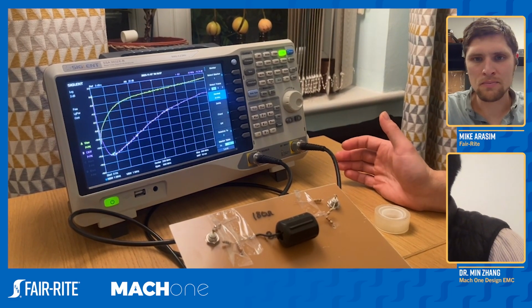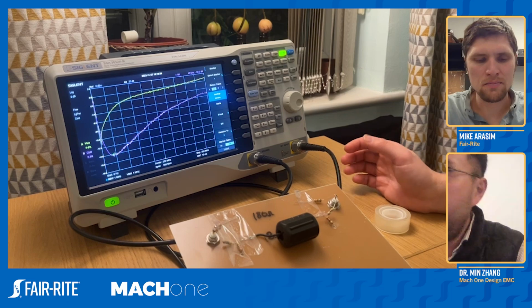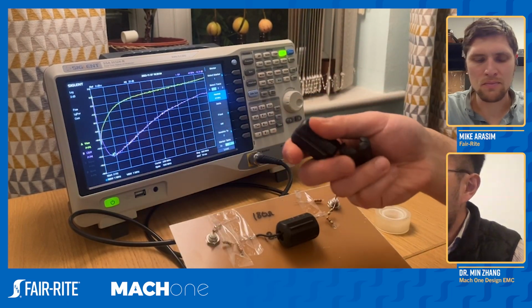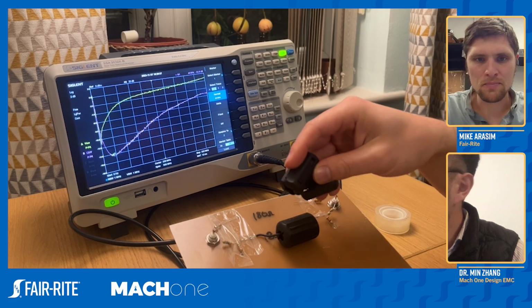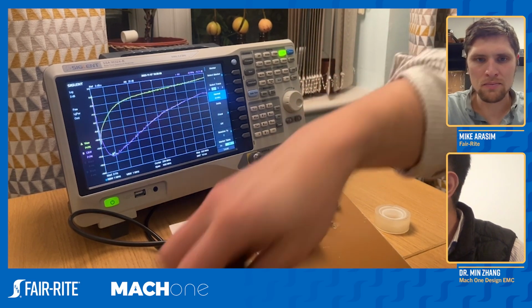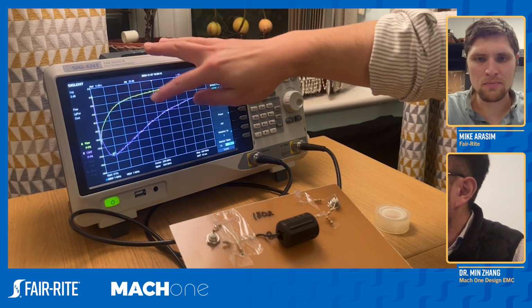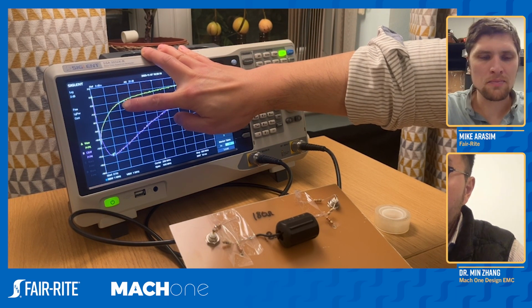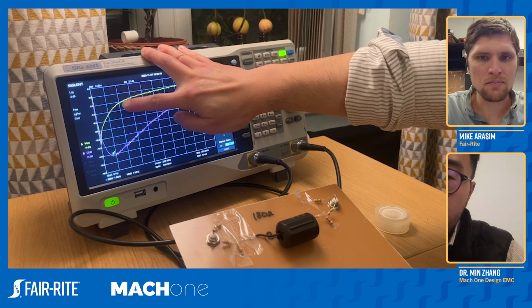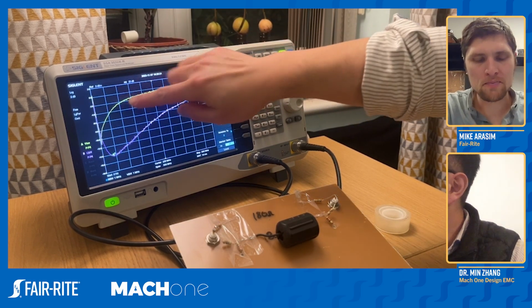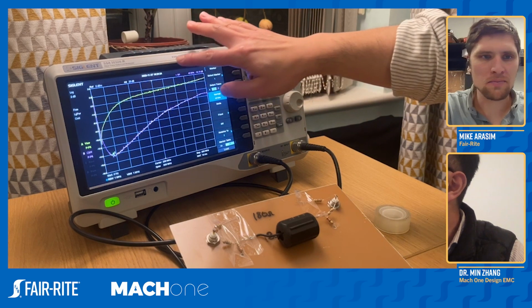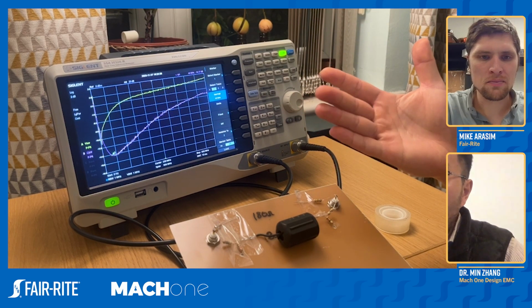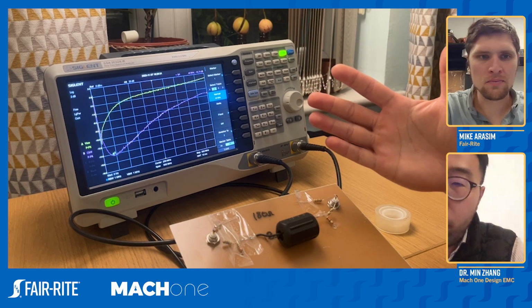At 40 megahertz, it gives me about 14 dB attenuation, and I can easily swap different ferrite core materials on the same wire. You can see there's a yellow trace, and that yellow trace is the 75 material I placed on the wire earlier on. So really, this is a very effective way of showing how different materials will have different impedance at different frequencies.